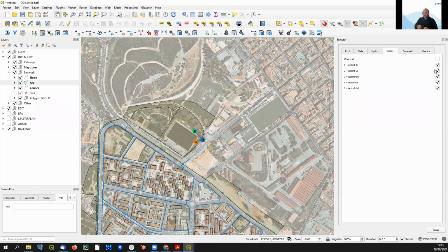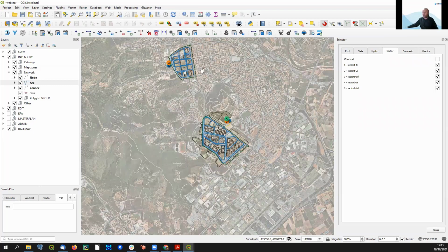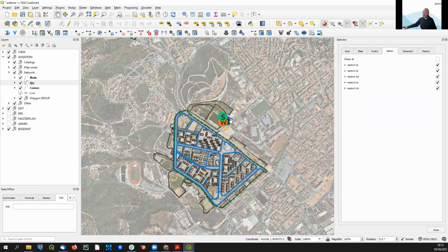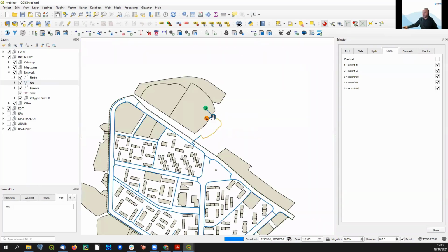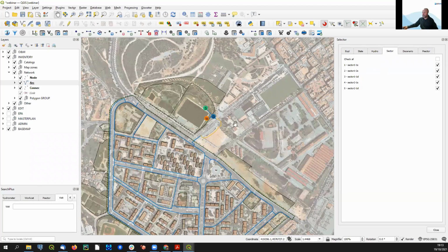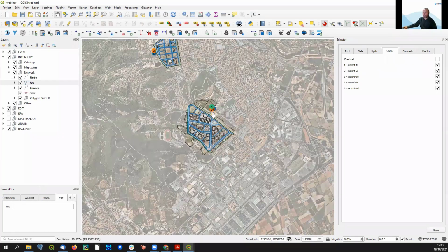It makes no sense to try to export only a junction. It makes no sense to try to export two pipes and three junctions. What is the minimum aggregation of elements to export to EPANET? The minimum aggregation of elements which has some kind of source, let's say a reservoir or tank. In this system, this minimum aggregation of one source related to one part of the network means 5 sectors. And I will work with these 5 sectors, exporting this first solution.